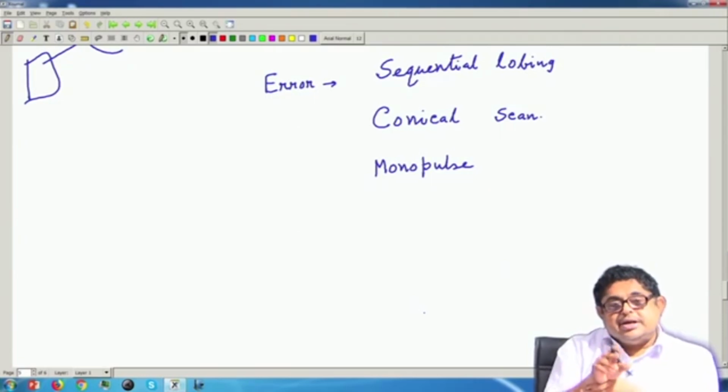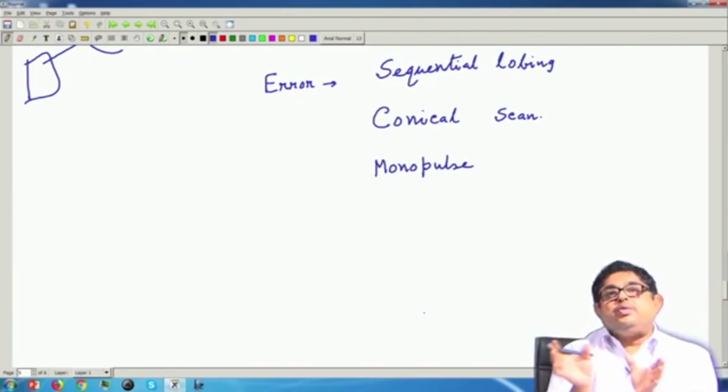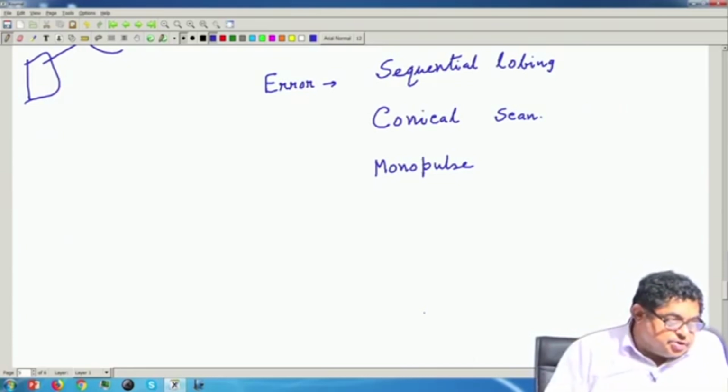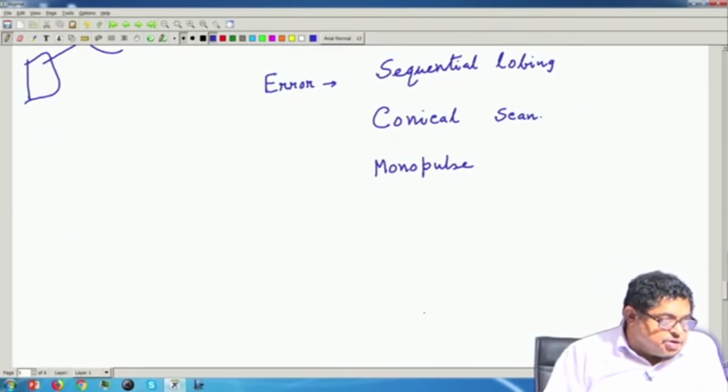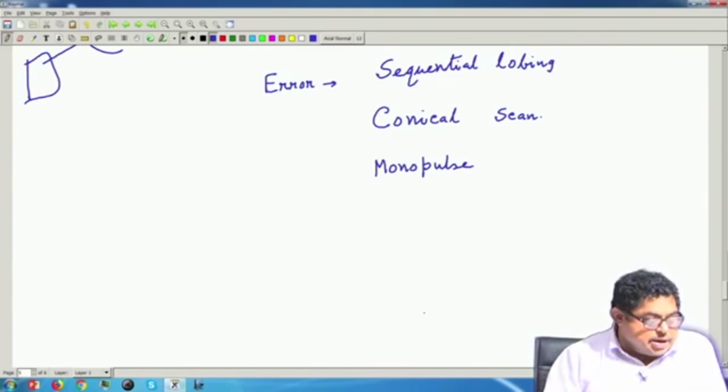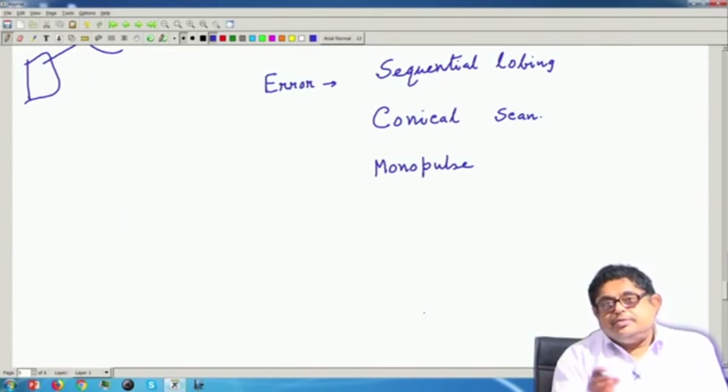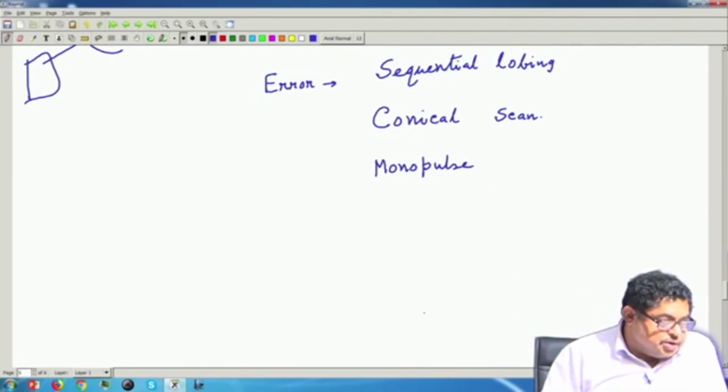If the radar says for two targets that there is only one target, then its resolution is poorer than the required separation of them. So, the resolution depends on the ability of the radar receiver to compare two signals, two echo signals almost equal.